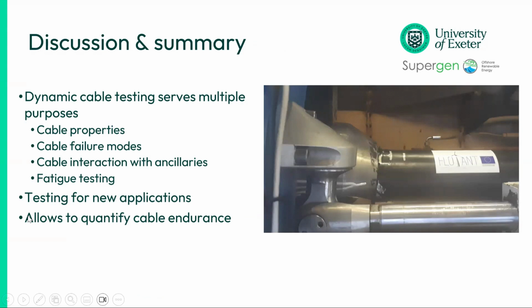So these were a couple of examples, and really I hope it showed that the physical testing and the dynamic testing of those cables serves a range of purposes. So there's not one test that fulfills them all. We've done tests where almost the question is only what are the cable properties, and that could be basically a test of a few days where we establish the bending stiffness and the axial stiffness of the cable.